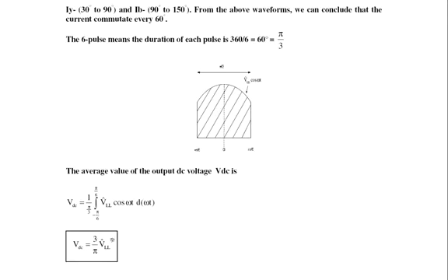So if you are given it in terms of phase voltage, you need to change that, and if you're given it in terms of RMS, you have to change to the peak value, and it has to be V peak line-to-line voltage. Okay,